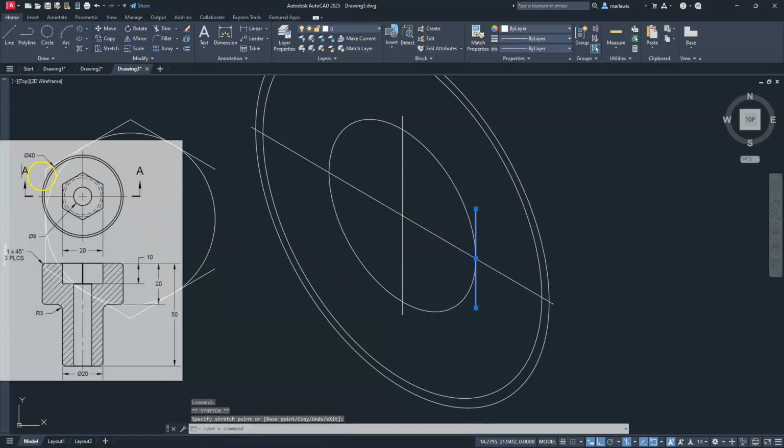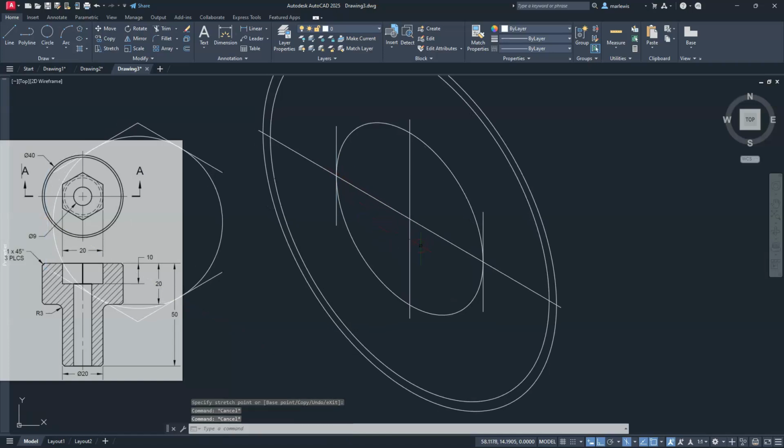The exact same thing on the other side here. So I'm just going to go ahead and select this line, select that grip, and then we're going to place it at that intersection on the other side. All right, so that's really pretty much all I need to create. Let's go ahead and draw a line now, connect these two endpoints, and the same on this side. Okay, let's do another line, and we're going to connect these two bottom endpoints, right? So we're going to connect an endpoint going here, and then one more going here.